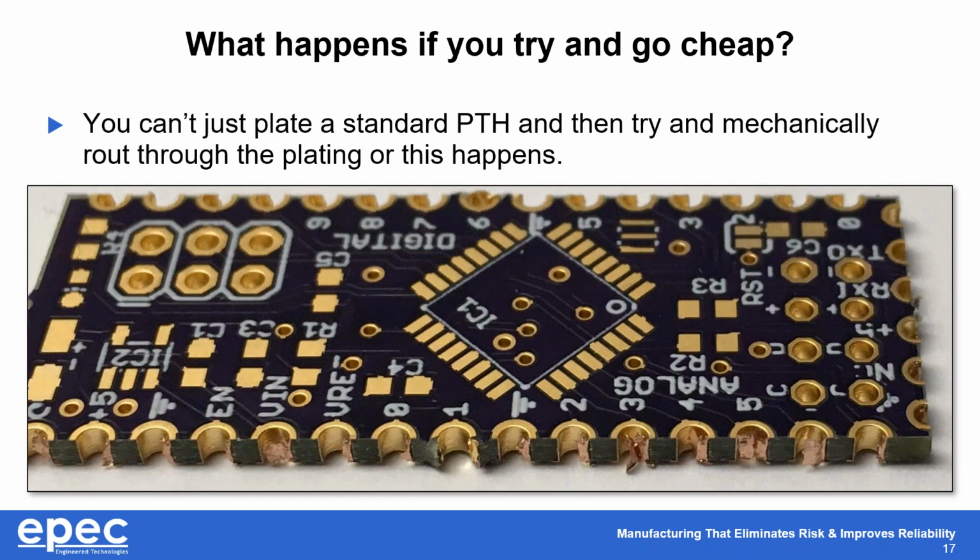And then what you get is what you're seeing in this particular picture, and that is all of that copper that came off of the other side of the hole. And you say, well, it shouldn't be a problem because it only came off of the other side of the hole. So many shops just take a good old-fashioned hard wire brush and wire brush all of those off of each one of those holes.